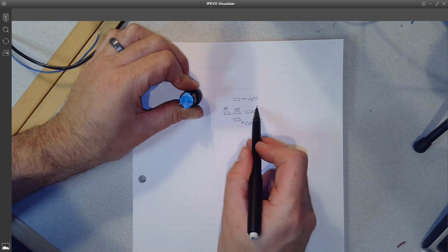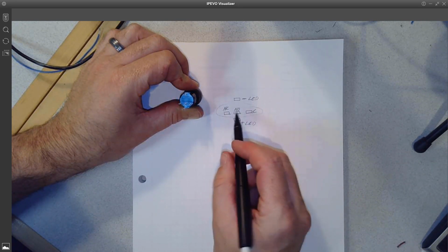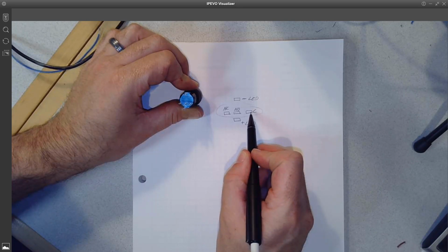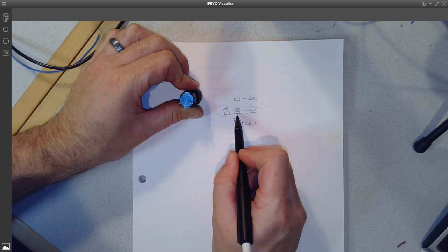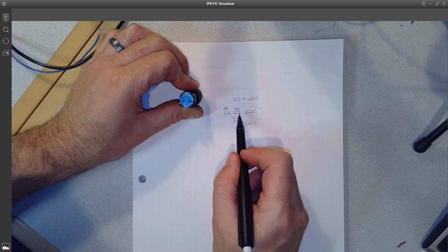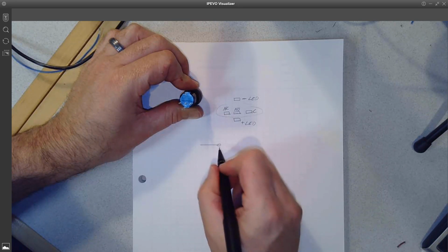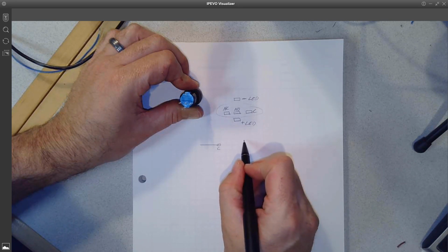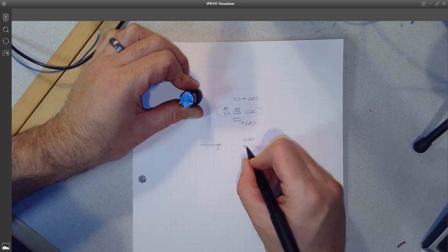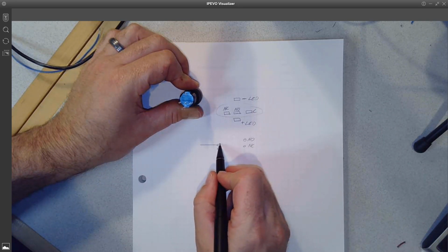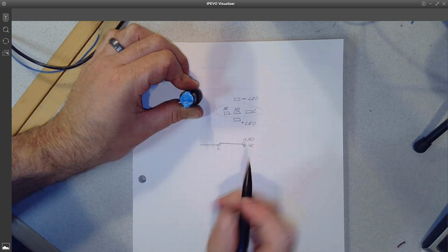So for this inner set, the button contacts, like I said a minute ago, that is a single pole, meaning there's one common that can go connect to other devices, and then a double throw, meaning there's 2 different options that common can connect to. So looking at it on a wiring schematic, it would look something like this. That's our common terminal, and then we'd have our normally open and a normally closed. So there's the contact, something like that.